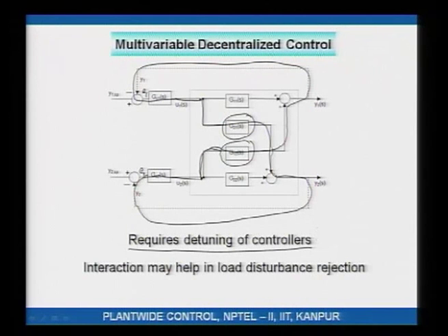So interaction actually creates additional feedback, and this additional feedback destabilizes your control system. What that essentially dictates is that you will require detuning of controllers because of the additional destabilization due to the interaction terms.